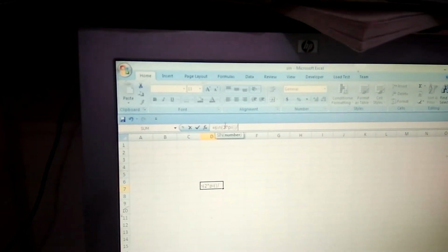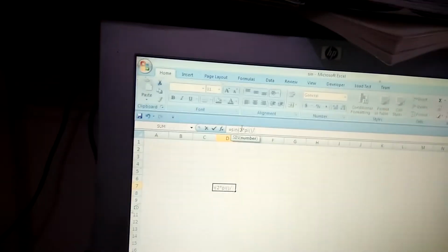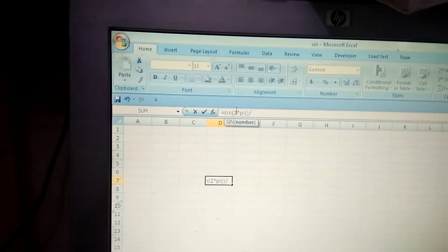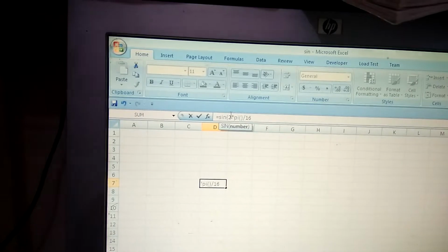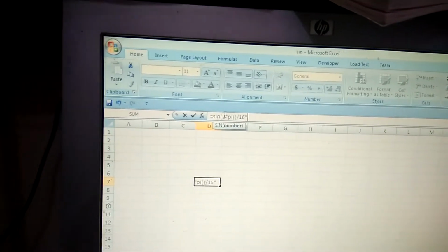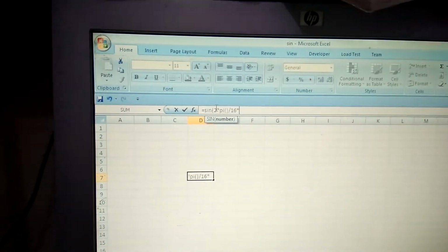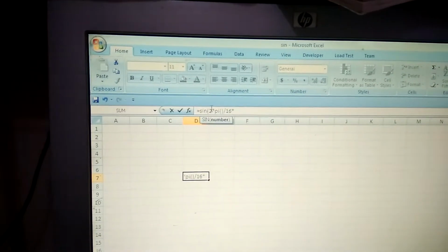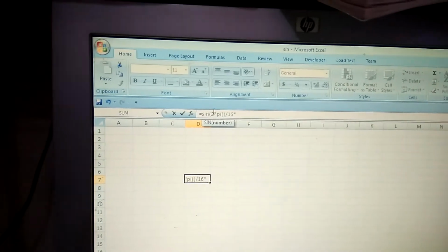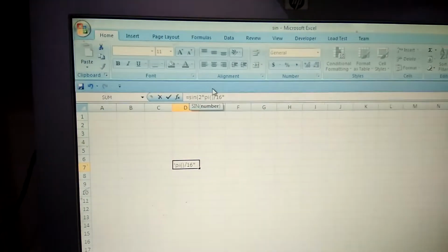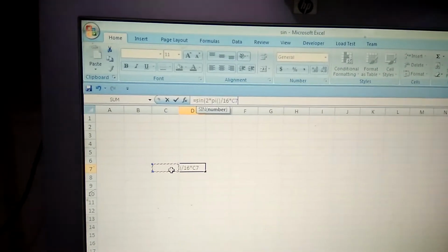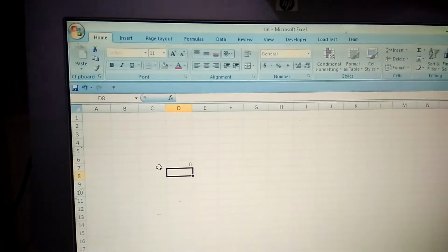Generally you can have 8 samples, 16 samples, 32 samples, or 64 samples. That depends on the precision, how fine you want to make the wave. Let me make it for 16 samples, so 2 pi divided by capital N, and here you have instances. So what is this instance? If you want to know the value at n equal to 0, 1, 2, 3, that n is going to be a variable, producing different values of sine. So you can select a different cell for giving a variable value. Just click on it.